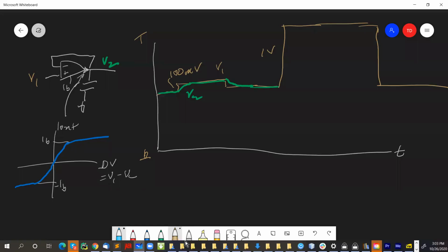So what happens when you charge a capacitor C with a constant current? It just changes linearly with time, right? So instead of going exponentially, usually a linear system is characterized by the bigger the signal, the bigger the response. That's what it means to be a linear system. In this case, the bigger the signal gets, it doesn't change the response. All it changes is that it has to go further before it becomes linear again. So now it'll go at a constant rate until the voltage gets small enough. And then when the voltage difference between V1 and V2 gets small enough, it starts going exponential again.